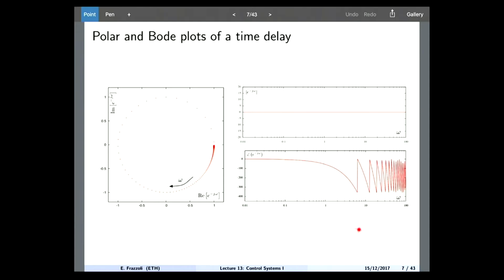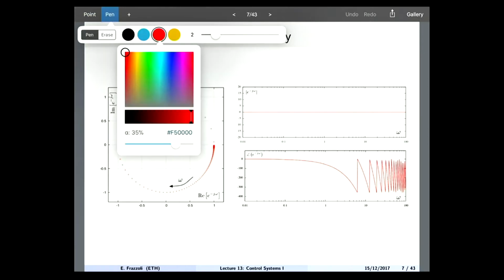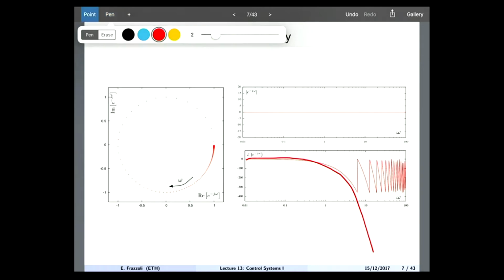So you can either draw it as an exponential just going down like that, or you can wrap it. However, you usually wrap the phase between 0 and negative 2 pi, and that's why you see all this up and down here. Clear? This is just the Bode plot of e to the power j omega t.